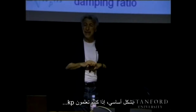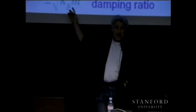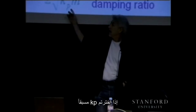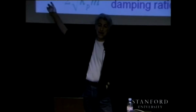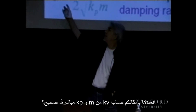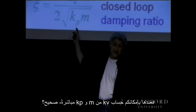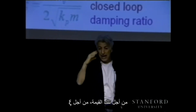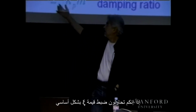So basically, if you already selected your kp, and if you want a critically damped system, then immediately you can compute kv from m and kp, for that value of zeta. So basically, you are trying to set zeta.